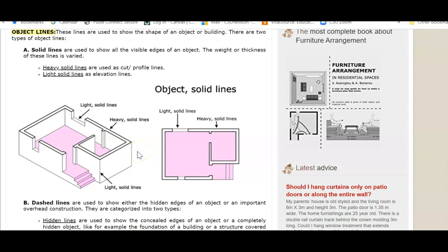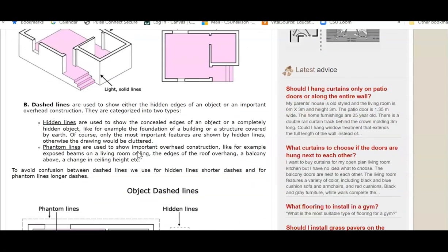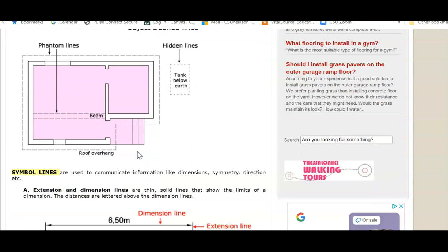We could also use this to emphasize perhaps columns in a darker line than something that is less important than columns. And depending on your firm, you'll typically have a standard line weight for each of these objects: walls, footings, columns, text, dimensions. We're also going to change the line type.